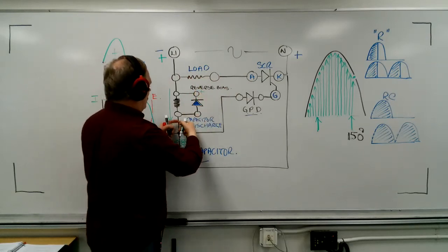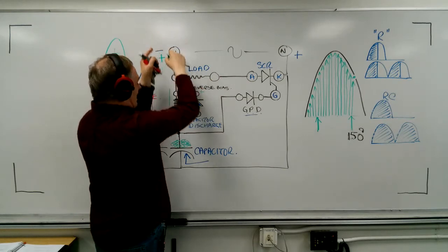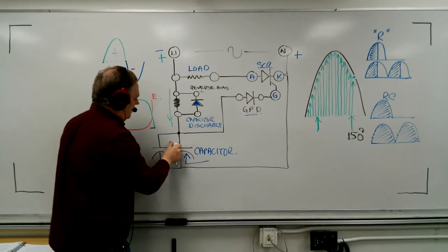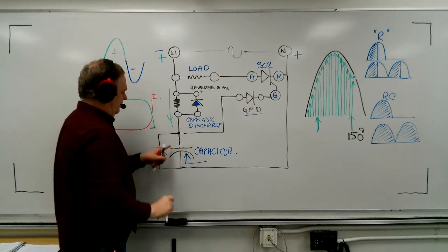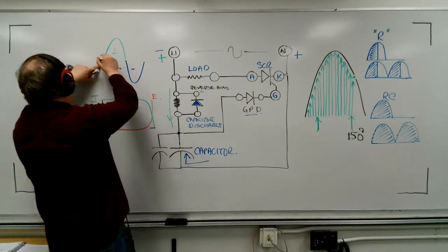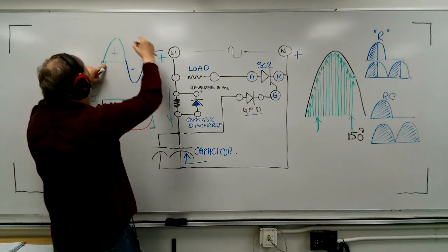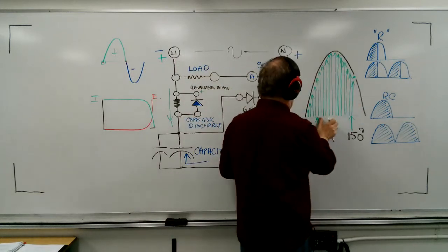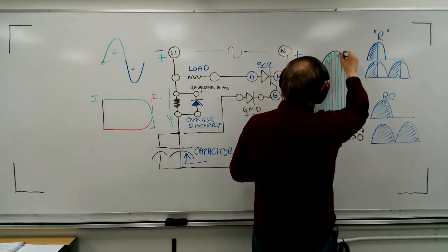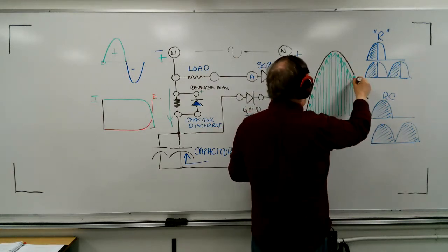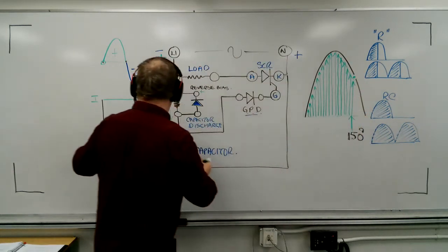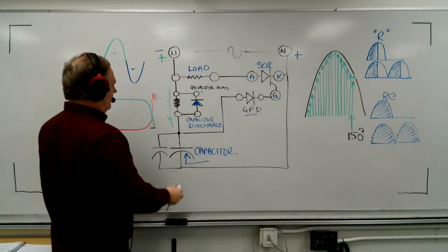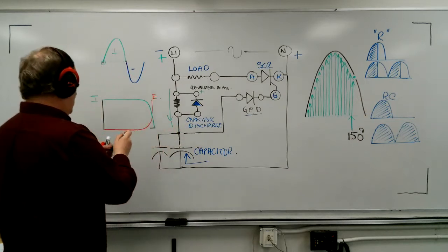It allows this charge to disappear back to the other line, and it leaves this empty and ready for the next fill. And the next fill will start here. And as this rises, the current will flow in, filling, filling, filling. Get to 90, it's not full yet. Continue on, down, down, down, and it will get to the exact same point. The voltage will shoot up at exactly the same time as it did in the previous positive alternation. So you'll get a constant firing angle.